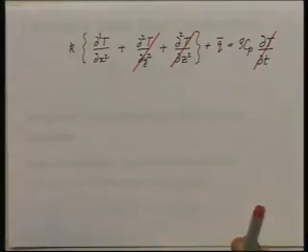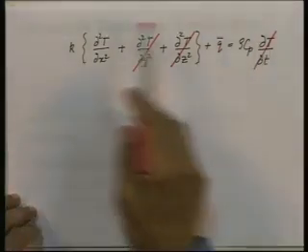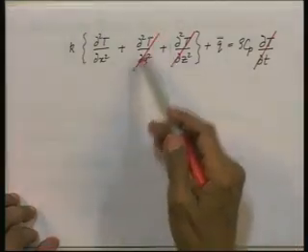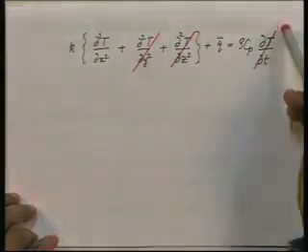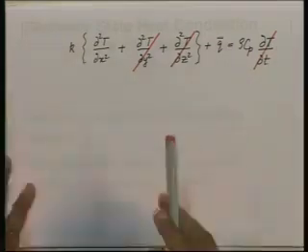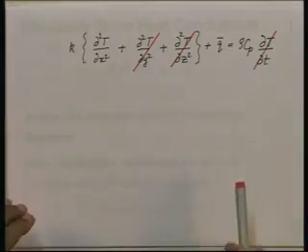So, if T is a function of x, y, z and time, this will be our differential equation with the d2T dy square, d2T dz square, dT dt term all being retained. Okay. So, obviously, life is going to be more complicated the moment we go to the unsteady state, because not only will T vary with space, T will also vary with time. So, straight away you are going to have a situation in which T is a function of at least one space variable and the time variable. So, straight away you will have a partial differential equation.